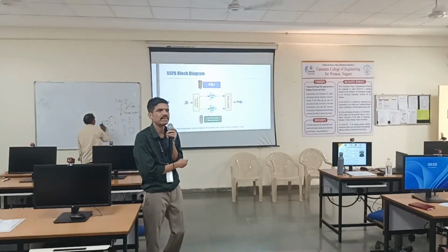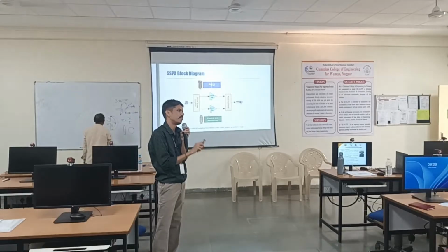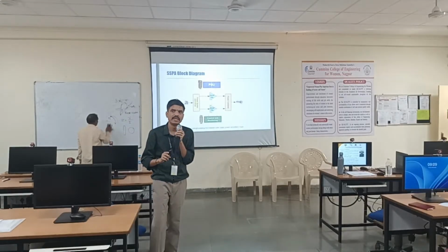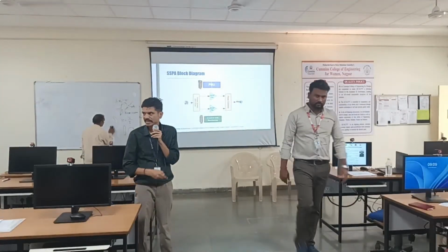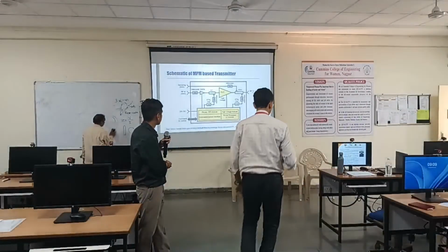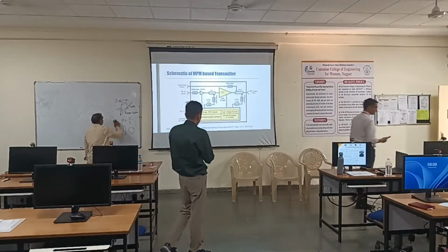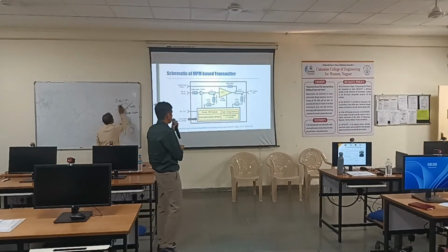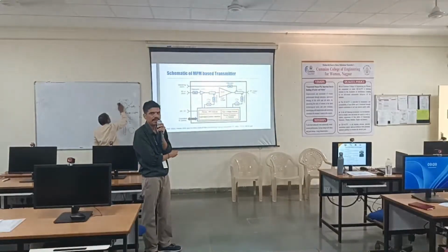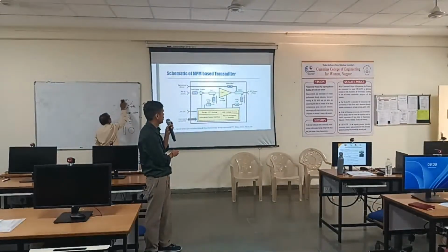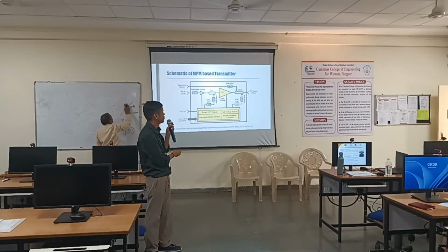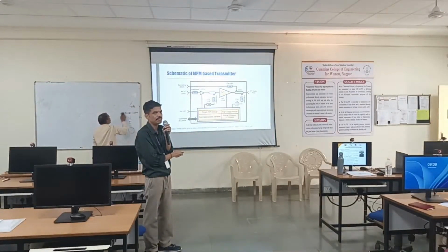So this concept is typically used in all microwave PA designs where you need very high power, called cascaded power amplifiers. Alright? Even in TWTs also, you can see certain stages: SSPA, pre-driver, driver, PA, then main PA. So 4, 5, 6 stages of SSPA will be there. Then you have a high voltage TWT, which will give you thousands of watts of output power.